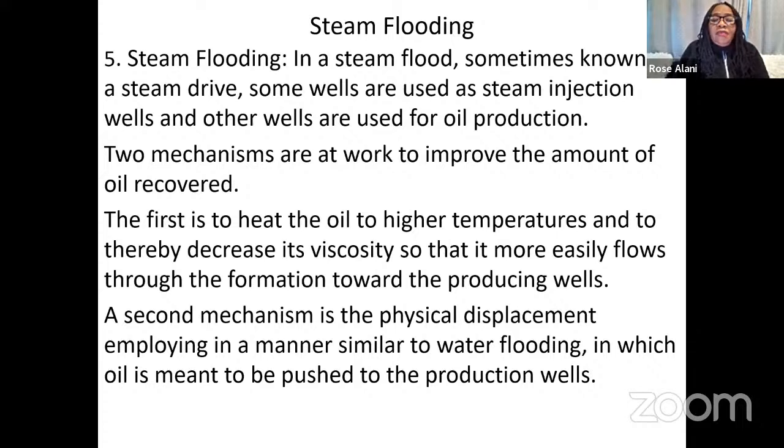The second step of steam flooding is similar to water flooding, where the oil is pushed to the production well. So the pressure is built. There are two stages in steam flooding. First, it decreases the viscosity. Second, the pressure pushes the oil out to the surface.